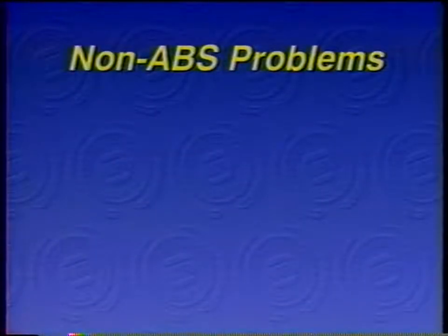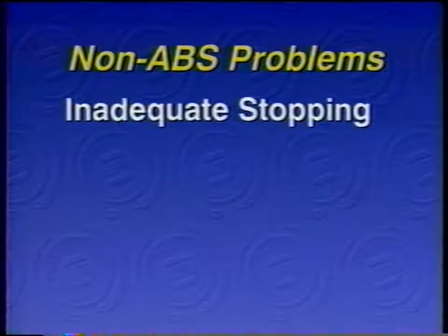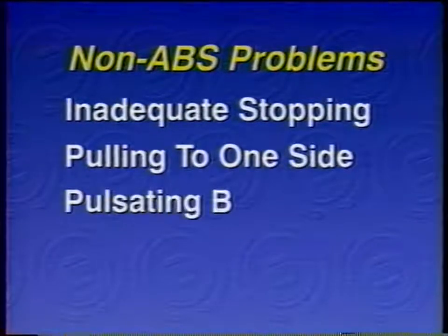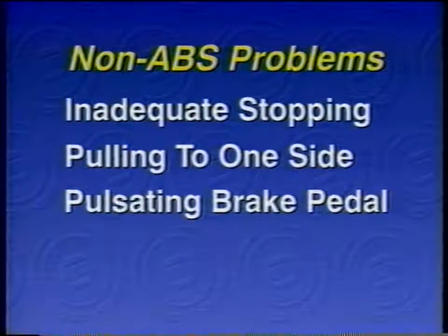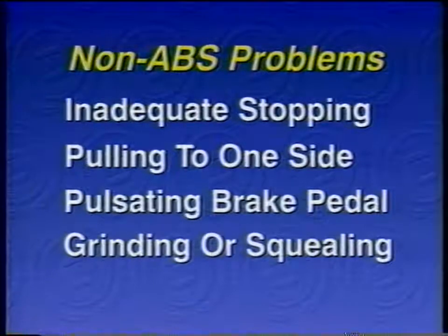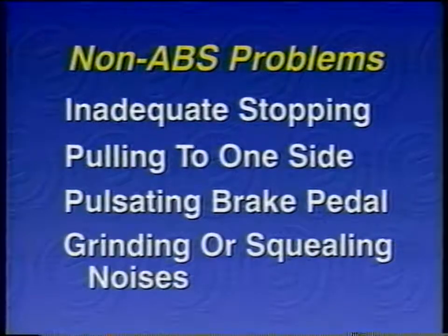As a general rule, inadequate stopping, pulling to one side, a pulsating brake pedal during normal stopping, and grinding or squealing noises are not ABS related. Isolate the sources of these complaints and repair them as you would any non-ABS system. Remember, a non-ABS problem could be masking an ABS problem. So check out the ABS system before returning the vehicle to the customer.